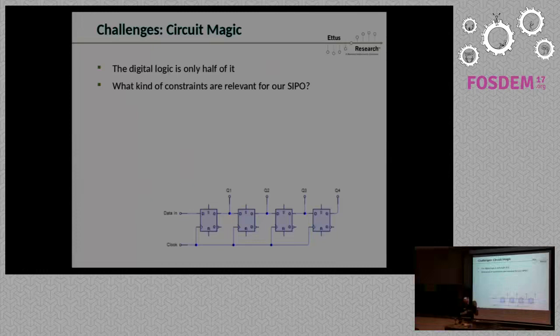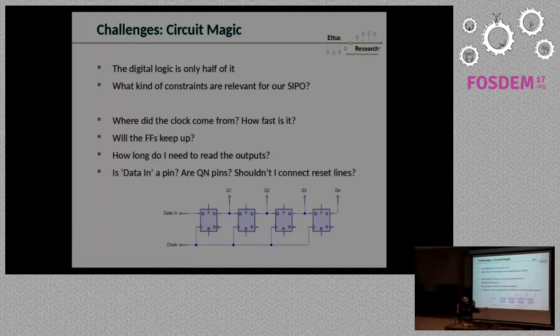What does that mean? Every flip-flop has a certain setup time: the data has to be applied before the clock is applied, and if the data in is asynchronous to the clock in. Okay, I don't want to go into that much detail, but I'm glad you did, because that emphasizes my point that you have this simple circuit, and then all of a sudden you have to think of all these things. I just randomly came up with these: where does this clock come from? Or how fast is it? And that goes slightly into your question, will the flip-flops keep up? Which is an unscientific way of asking the same question.